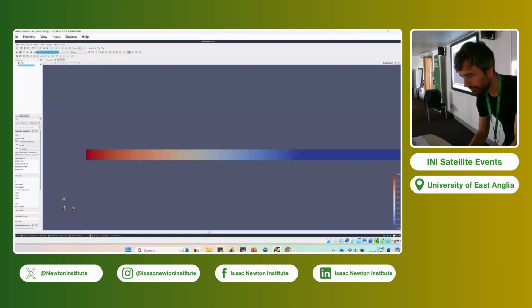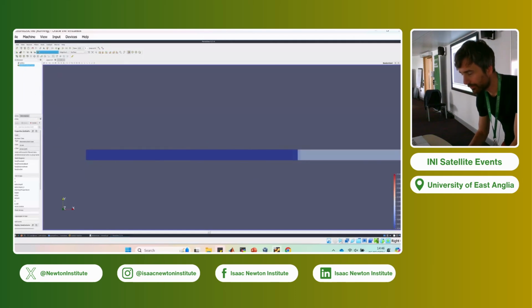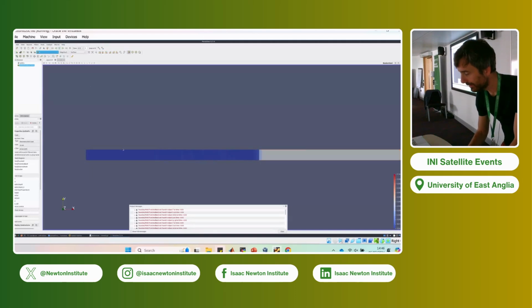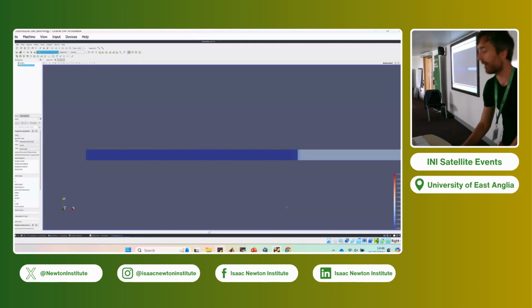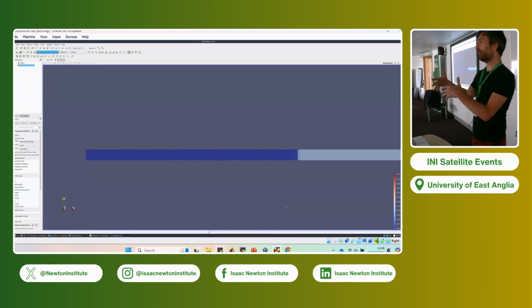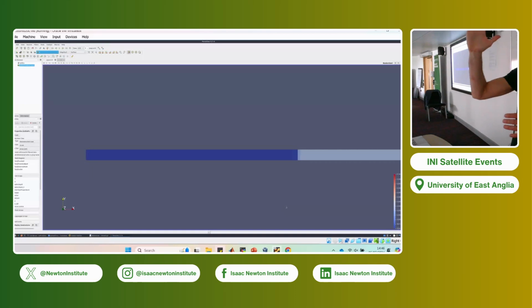And we can also see the velocity of the flow, that over time the interface moves to the right, but the velocity slows down because, if you remember well, the interface moves with the square root of time, which means that the velocity at which the interface will move will evolve as 1 over the square root of time, derivative of the location of the interface. So over time, the velocity of the fluid should decrease.